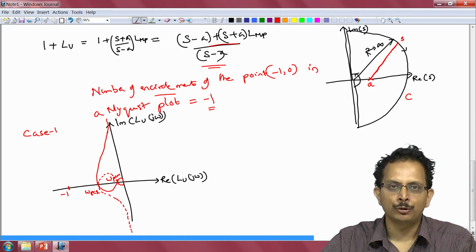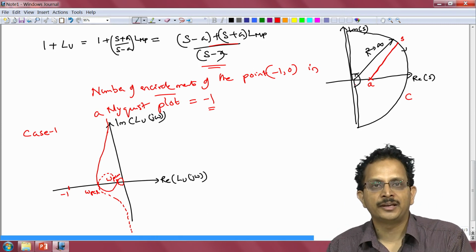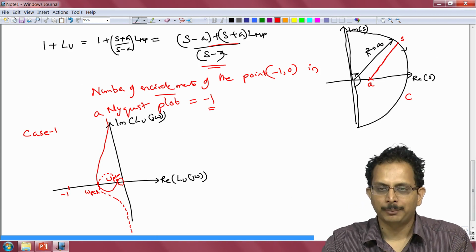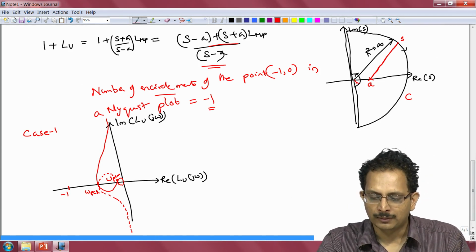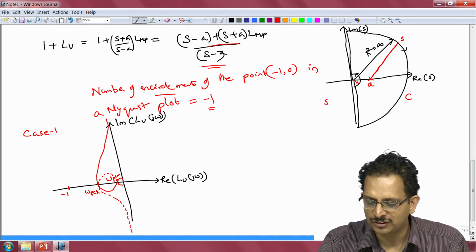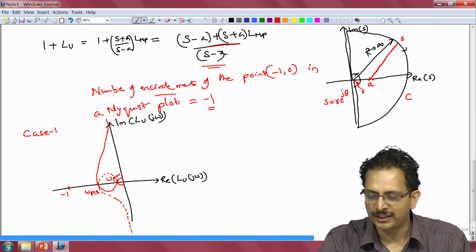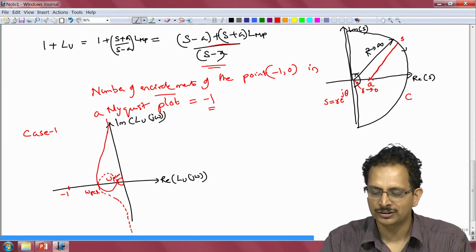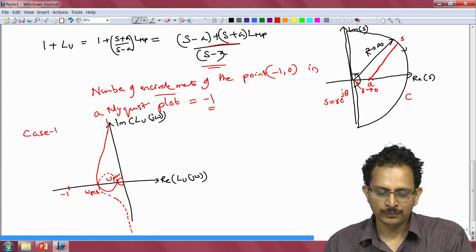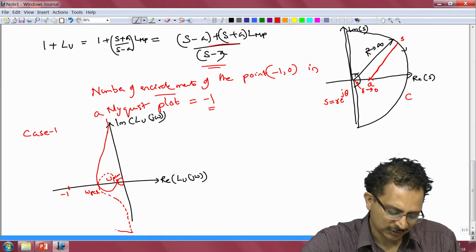The big D shaped contour will collapse to the origin, and what about this small semicircular kink that we have introduced that avoids the integrator at the origin? We can show that by substituting the expression that along this contour we would have the complex number to be of the form s is equal to small r e power j theta, where small r is the radius of this kink and that is tended to 0 of course, and we see that theta here goes from -pi/2 to +pi/2. We can show that this particular curve gets mapped to a big semicircular arc.